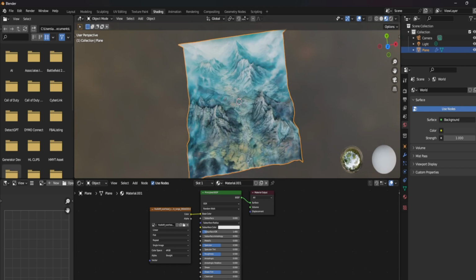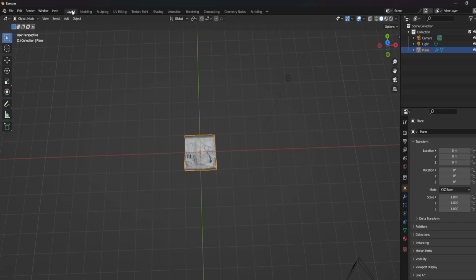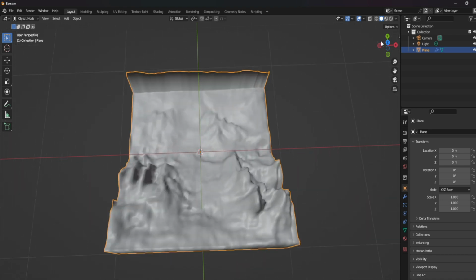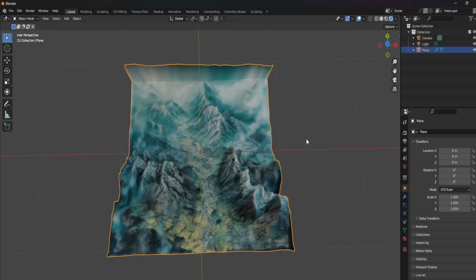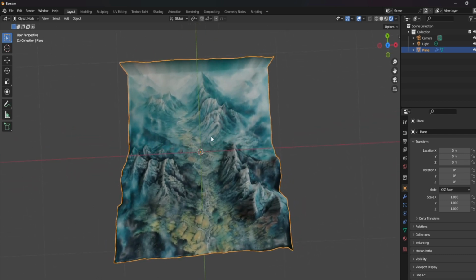From here, let's go ahead and go back to layout, and on the top right, we actually want to see our image with all of the coloring. So let's go ahead and Control plus, we will zoom in a little bit, and on the top right, we're going to click the furthest right bubble. That will be viewpoint shading, which will let us view our image, or our 3D render rather, with it completely shaded.